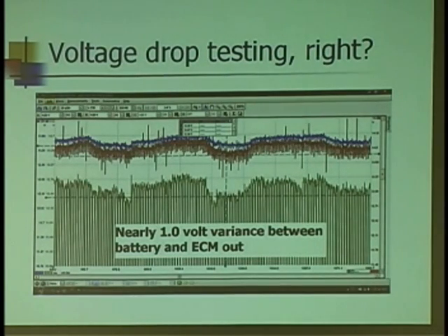And if I look at where my leads are, one's on the battery, one's right at the ECM for the field, it's got to be between the 2 points, right? So it's between the ECM, the power going to the ECM, the fuse box, the cable, back to the battery. And how am I going to find it from there? You start moving back towards the battery until it returns to normal. And that's how we isolated something very simple. It turned out all it was the section of positive battery cable going from the battery to the fuse box. That cured the flickering light problem.